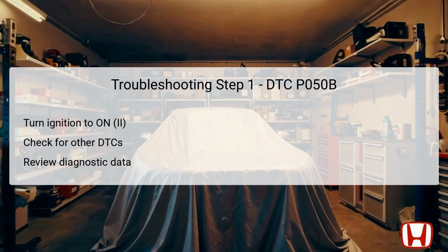The HDS allows you to document freeze data and any onboard snapshots, which are essential for understanding the context of the current or past issues faced by the vehicle. This comprehensive review helps in formulating a clear diagnostic pathway before proceeding directly to code-specific solutions. If no additional DTCs are found, you can confidently move to the next step in the diagnostic sequence.